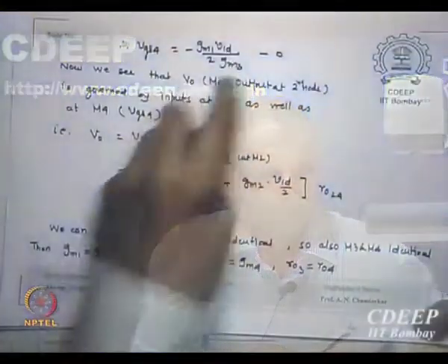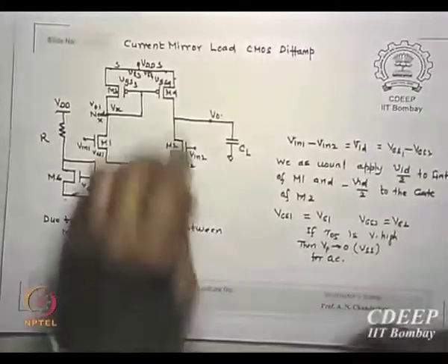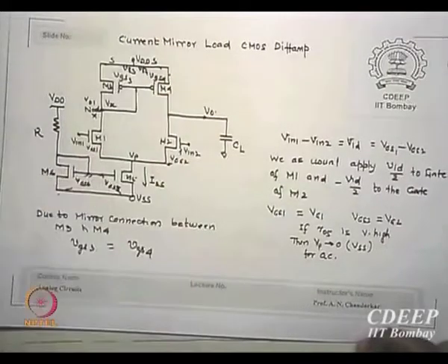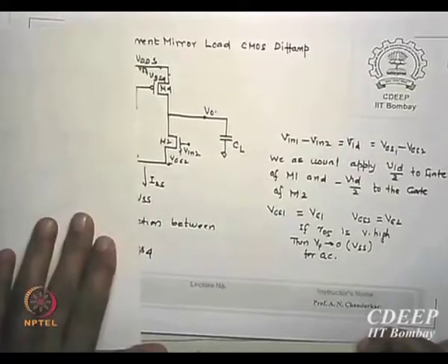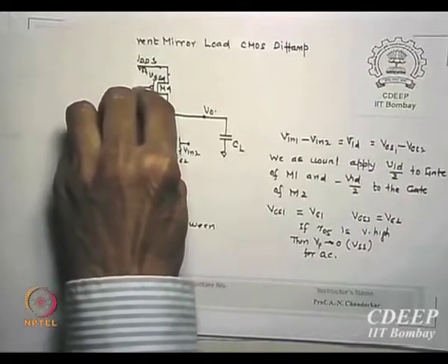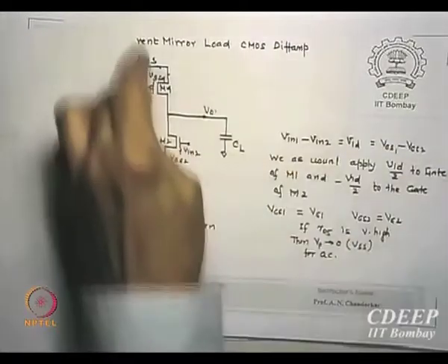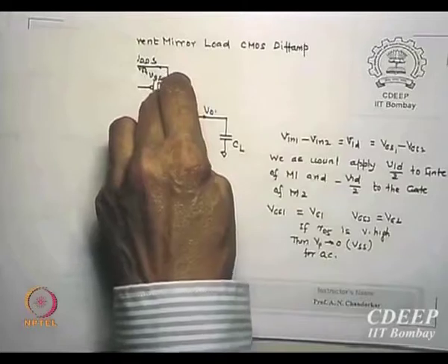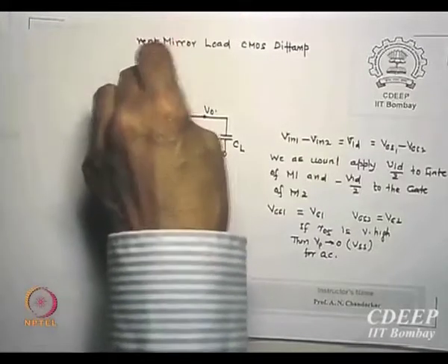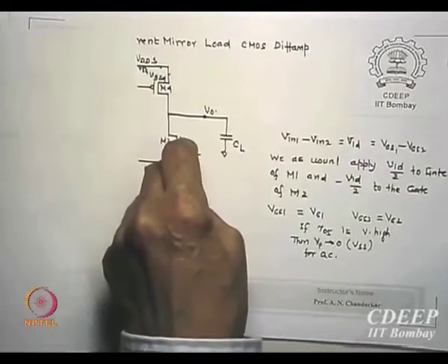Okay, so having done this, I calculate VGS4, which is GM VID by this. Now I have this M2 M4 amplifier. The VO is decided by how many inputs? M4 is also an input, and M2 also has an input. So the output voltage, by superposition, will be the part available because of this plus the part available because of this.